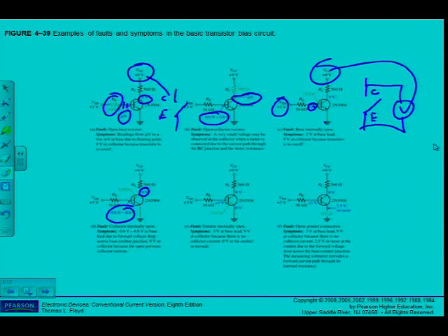So the transistor again acts like an open switch, but in this case, because of the measurement that I made at the base, I can see that the base is working fine. It should be the collector that is internally open. If everything is working up to the collector terminal, it must be internally that the collector is open.